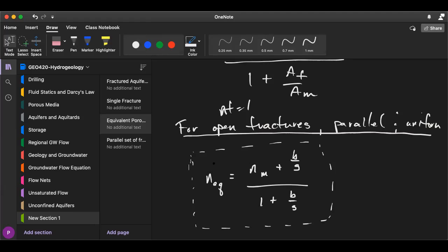I've given you fracture aperture that we estimated, and I've given you some estimate of the likely porous media matrix hydraulic conductivity and porosity. What you have to do is calculate the effective hydraulic conductivities using these equations, all right? Then we're going to see how those compare to what we measured with the slug.